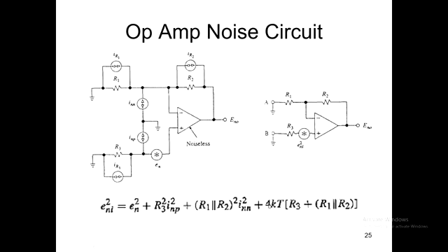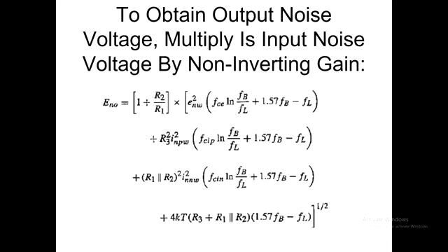Well, it's the square root of 4kT R3 or any resistor. Now this is spot noise again. It's spot noise because it's only at one particular frequency. And then we would have to multiply this by a big bandwidth. So we're nearly there though. We're nearly there. Oh, no we're not, damn it. Just when you thought it wasn't getting complicated.